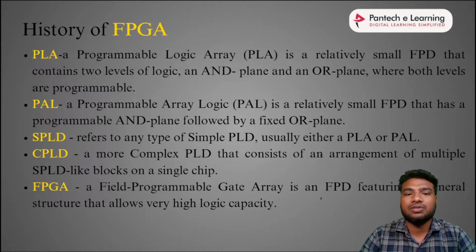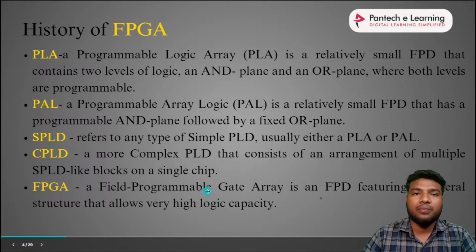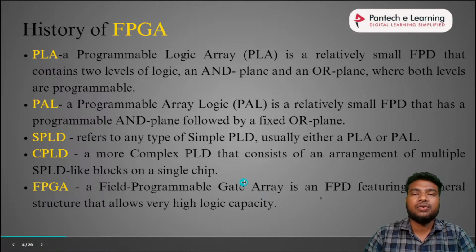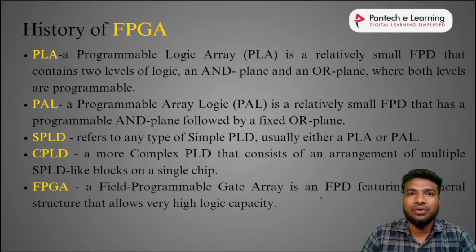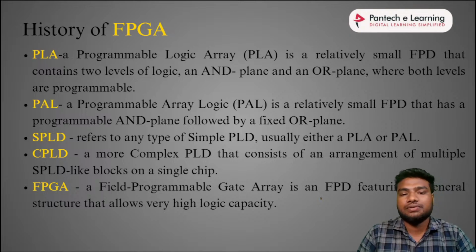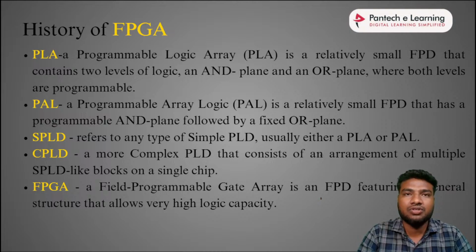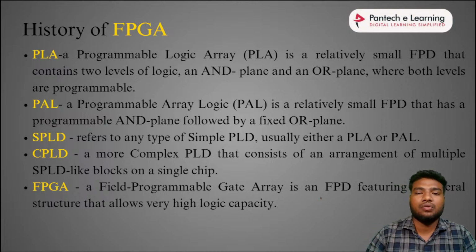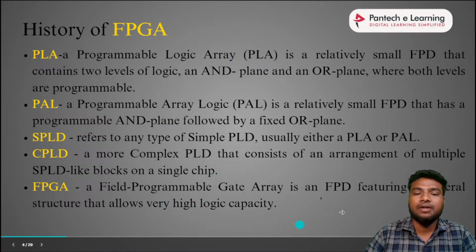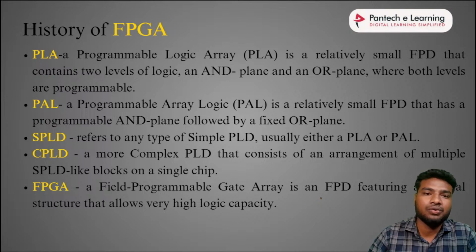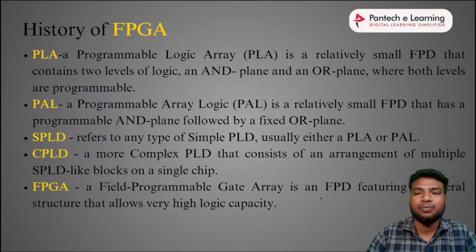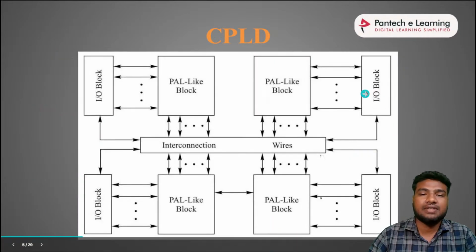If you take any sequential circuits, we can do them in FPGA. If you take any combinational circuits, we can do them in FPGA. For sequential circuits, we have flip flops. It also has lookup tables. A lookup table is like a mux or SRAM, and it stores the previously computed data. I will show in an upcoming slide how a lookup table looks. So the FPGA has lookup tables, muxes and flip flops. We can make any digital circuit in the FPGA by using a software tool to implement the FPGA hardware code into the FPGA board.